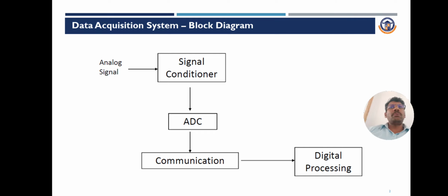This front-end pre-processing is generally referred to as signal conditioning, which includes signal amplification, filtering, electrical isolation and multiplexing. In addition, many transducers require excitation current or voltage, bridge completion and linearization or high amplification for proper and accurate operation.